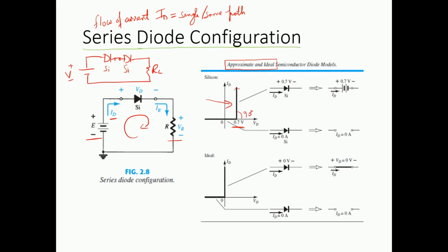In our circuit analysis, we are going to replace the symbol of the diode with its equivalent model to make our analysis or KVL a bit easy or understandable. If we are using the forward bias condition shown over here, our circuit's symbols and behavior will be such. If we are in the reverse bias condition where there is no conduction, then our diode will be replaced by an open circuit. And if we are talking about the ideal model, then at 0 volts, when VD is equal to 0, we are going to have the maximum current, which means that our diode symbol is going to be replaced with a short circuit, and we know in a short circuit from Ohm's law the voltage is 0 volts. And if we are in the reverse bias condition, for the ideal case, our diode symbol will be replaced with an open circuit. So again, these are the things which we have seen in our previous lectures, but just to refresh your memory, they have been introduced over here.